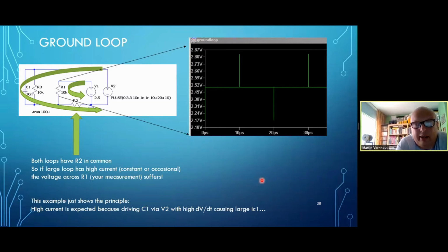Right, electronics to the rescue. What we suffer from most are ground loops. That means your ground, that's the 0 volt node somewhere, that is not taken lightly. If this is your ground node and we have connected multiple paths, every bit of trace has resistance. They actually sum up in the resistance they have in common. So careful that you don't create ground loops.